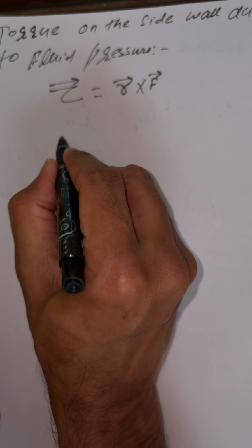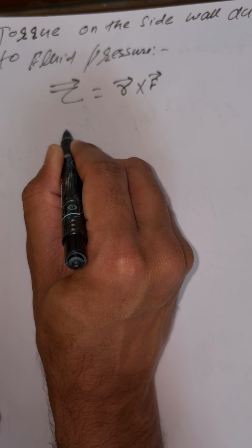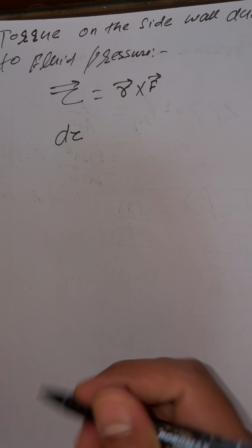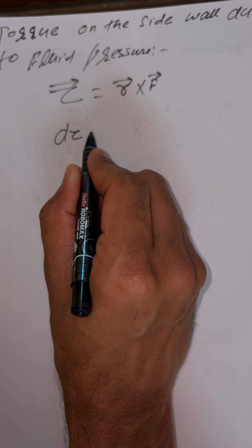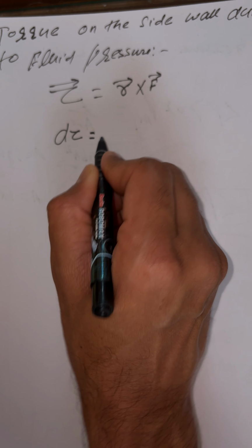So students, because we wish to find torque, I shall write d tau for a small element, right? Because again, it is not possible to write torque directly as R F sin theta. Here torque is force dF into the perpendicular distance. What's the distance here? This is y, so this is H minus y, my dear. So this is the expression of torque.